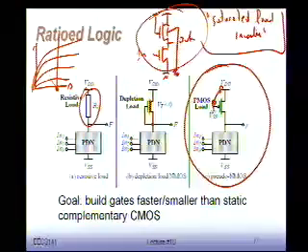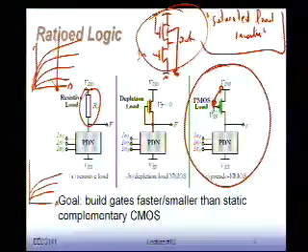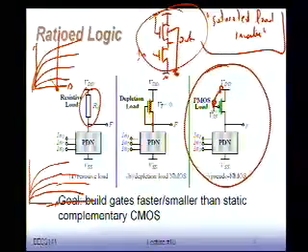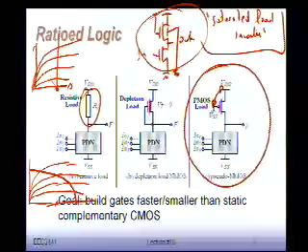So if I now look at the current characteristics, this is my NMOS transistor. My PMOS load will look something like a PMOS with a particular load factor, like this. Right, that's my PMOS device with VGS equal to VDD.